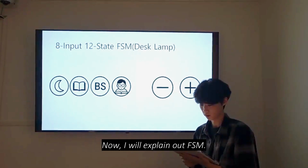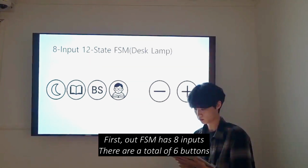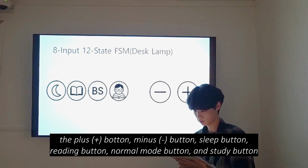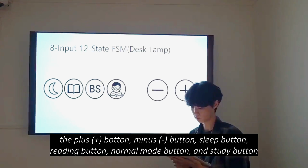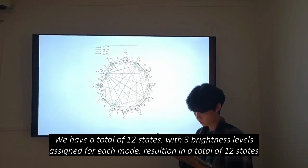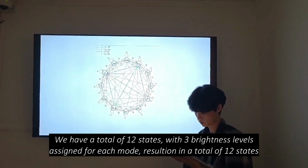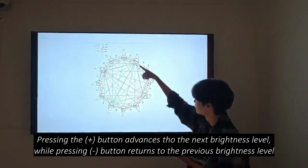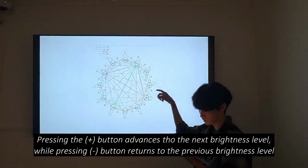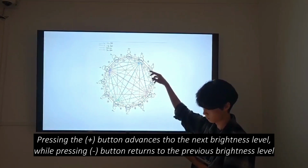Now I will explain our FSM. First, our FSM has 8 inputs. There are a total of 6 buttons: the plus button, minus button, sleep button, reading button, normal mode button, and study button. We have a total of 12 states, with 3 brightness levels assigned for each mode. Pressing the plus button advances to the next brightness level, while pressing the minus button returns to the previous brightness level.